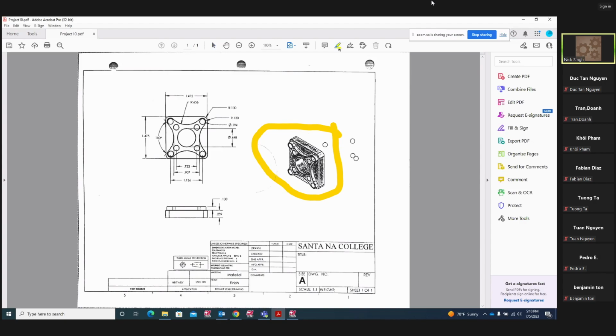If you have live tooling, C-axis, called C-axis live tooling. So what we can do, we can turn the round stock diameter first into 2 steps, and then we can mill this with the C-axis.